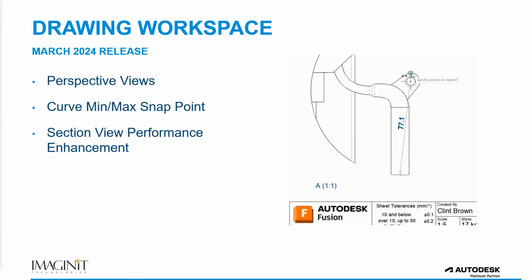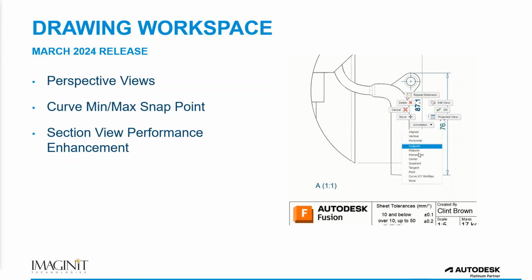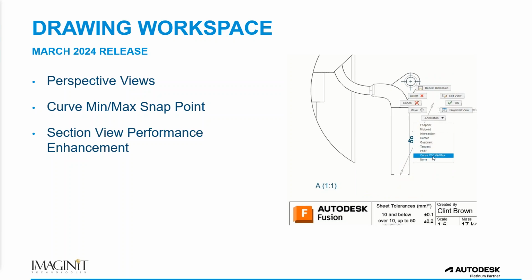Next up, we've got curve min and max snap point, and that's actually what you see in this GIF here on the side. So what's happening here is we're using that curve geometry to grab the top and the side of that boss by using the maximum point on it. You might think of this in terms of maybe AutoCAD as quadrant, if you were familiar with that. In this case, though, it's just grabbing those as the maximum or minimum extents of that curvature.